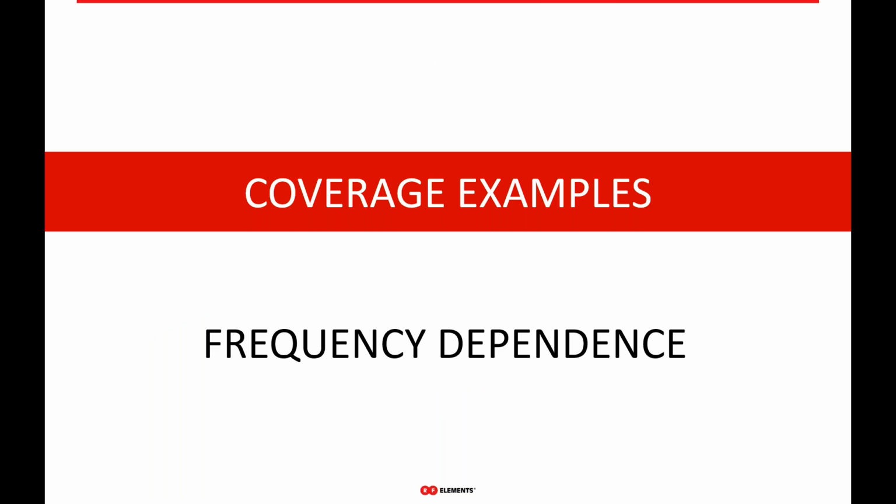The plots on the previous slides are showing only static images of the coverage at one particular frequency, which is something that's really important to understand, even when you read spec sheets, right? In spec sheets, you're looking at some hard-coded parameters for gain, beam width, and all this other stuff, and it's typically at a particular frequency. So if we were to calculate the coverage at many frequencies and make an animation of these images, we could see how the coverage changes with frequency, which is something you typically don't see in a spec sheet, and most manufacturers never really talk about.